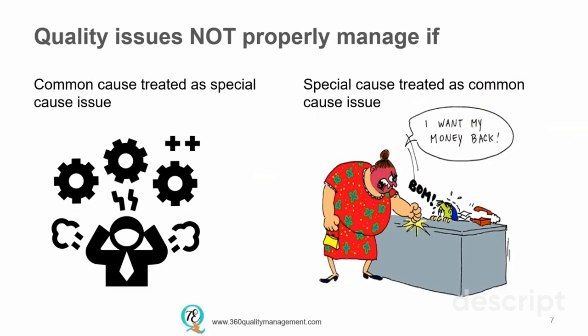There has been a lot of confusion in distinguishing these two types of special cause and common cause process inputs which cause failure. Treating common cause process variation as special cause will drain the resources, as it is not possible to eliminate common cause variations under normal circumstances. A good example will be surface particles, which have a very low reject rate on a product. And as we know, particles exist everywhere, which is a common cause variation. And we have to take extreme measures if we want to eliminate particles, such as producing the part in a vacuum or in outer space where there's no particle. And this is really not an economically viable solution.